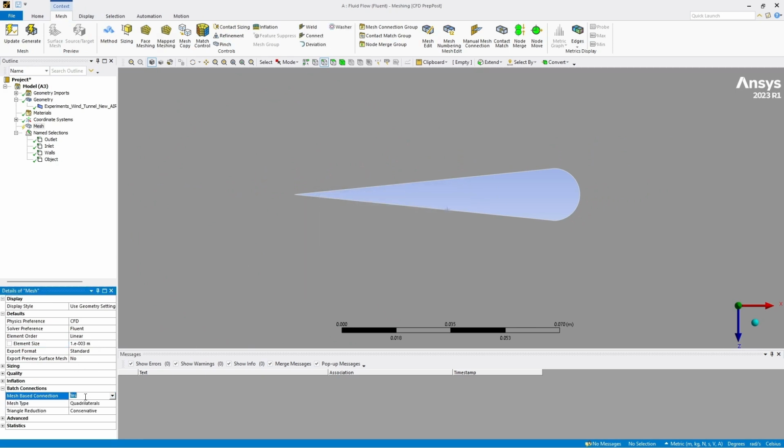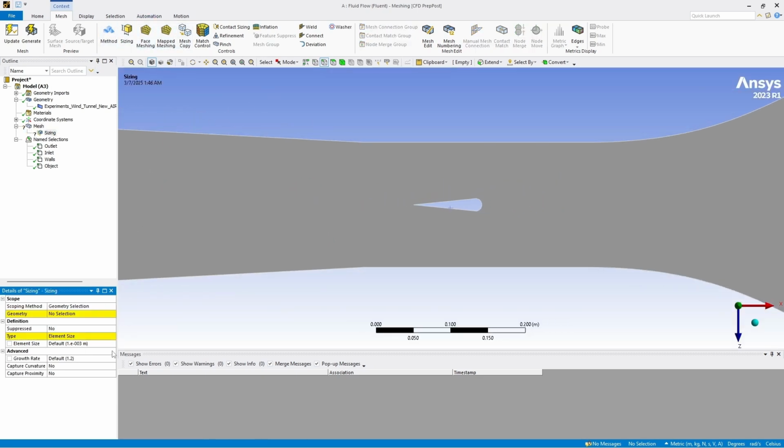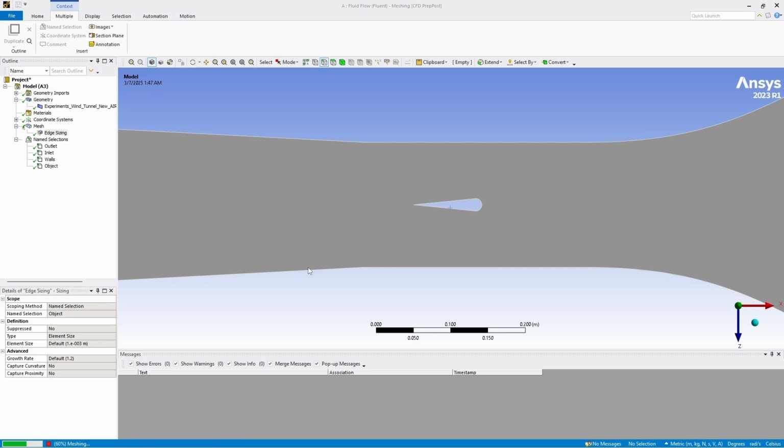So normally, one way we could just do this mesh is brute force it completely by just lowering the element size to like 0.0000001 meters. But the problem is your computer might not like it. It might not even load. It'll take a couple hours. You can really go overkill in the mesh. But that's not really practical, especially in like a professional environment.